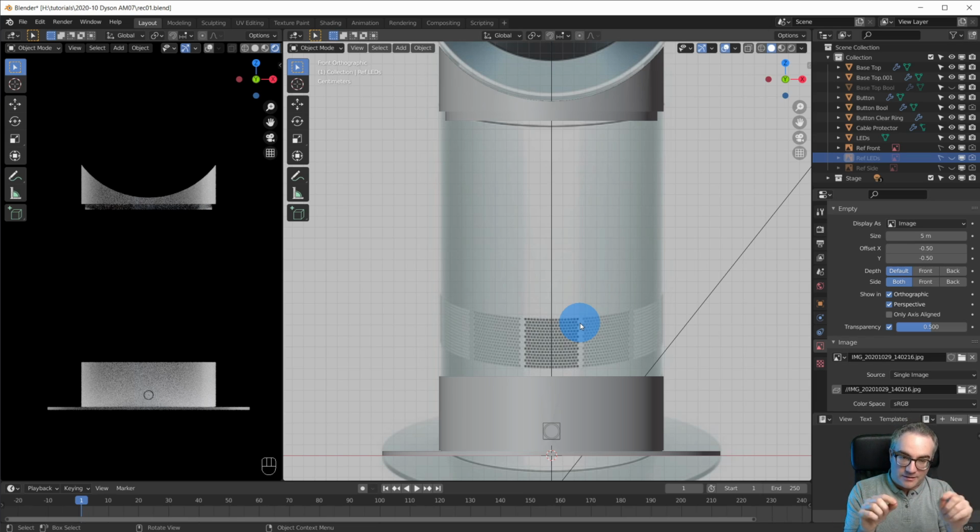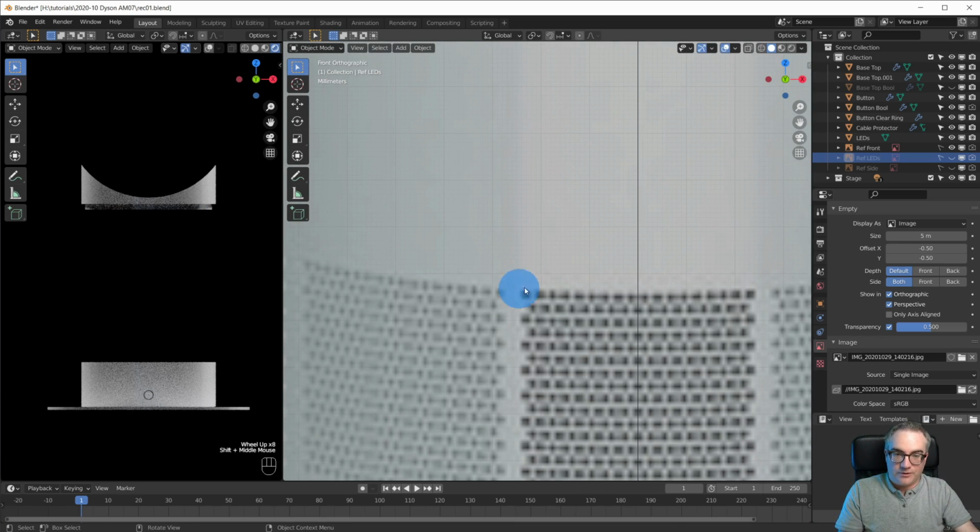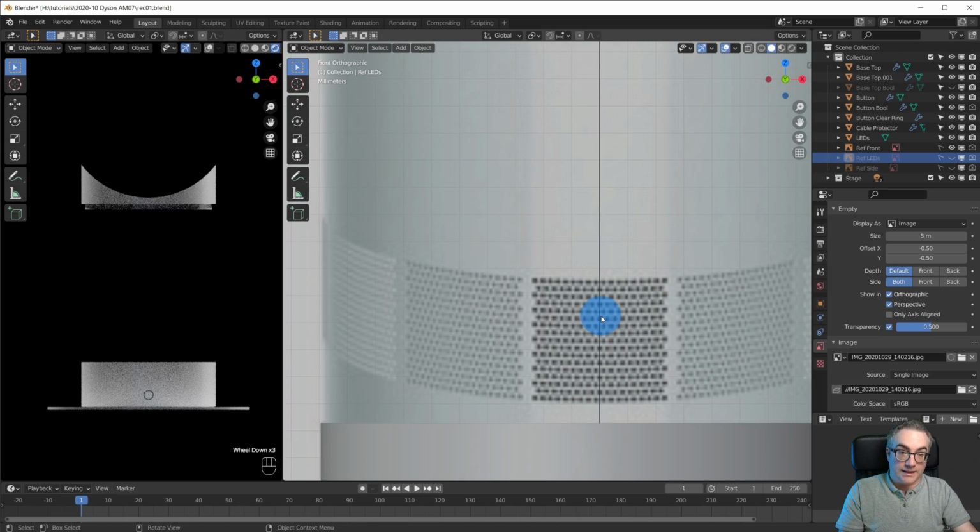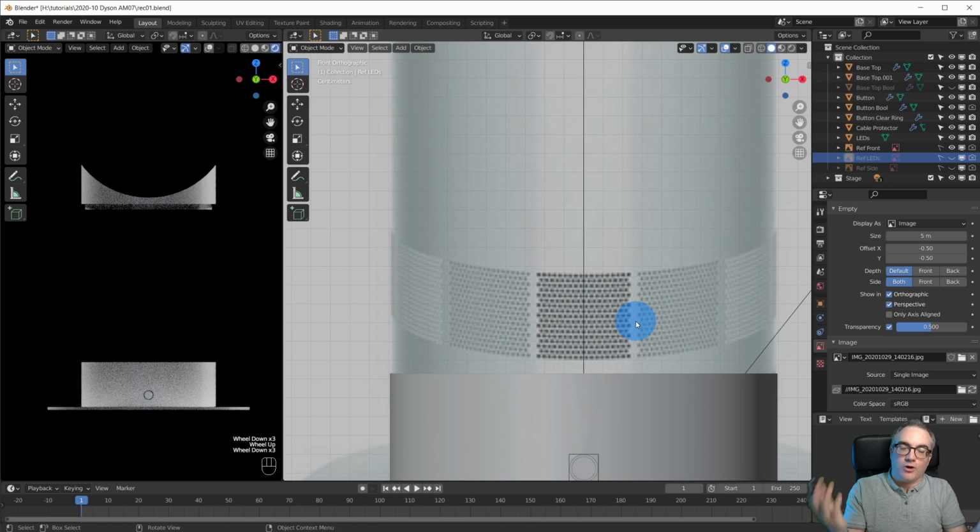And then the other row, the one that's offset a little. So this would be the first set here, and then this is the second set, which has this offset and fewer holes basically, and then create all of these holes in 3D, and then cut those out with a Boolean modifier of that center cylinder.